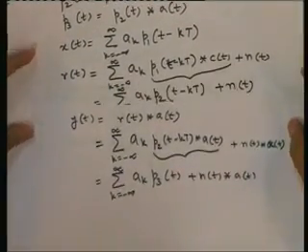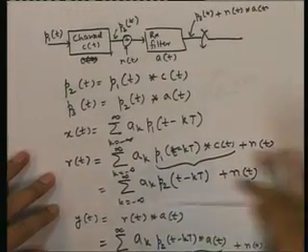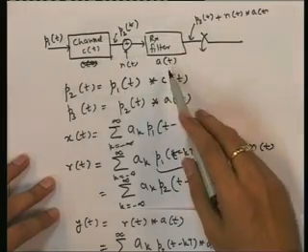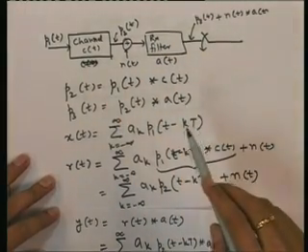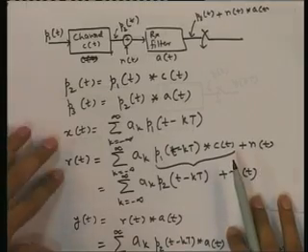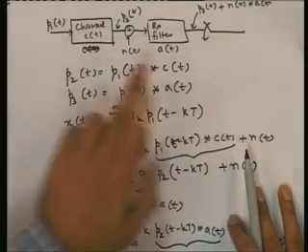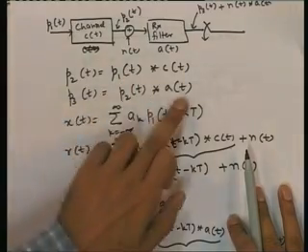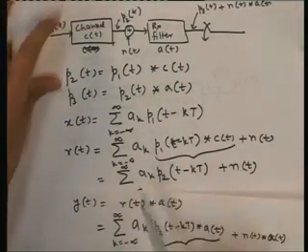So what do we have? We have assumed the response of the channel to p1(t) to be p2(t), and c(t) is the channel response, and the receive filter impulse response is a(t). Then p2(t) can be written as c(t) convolution p1(t), and p3(t) can be written as p2(t) convolution a(t). And x(t), we know, is a PAM signal, so it is of this type.